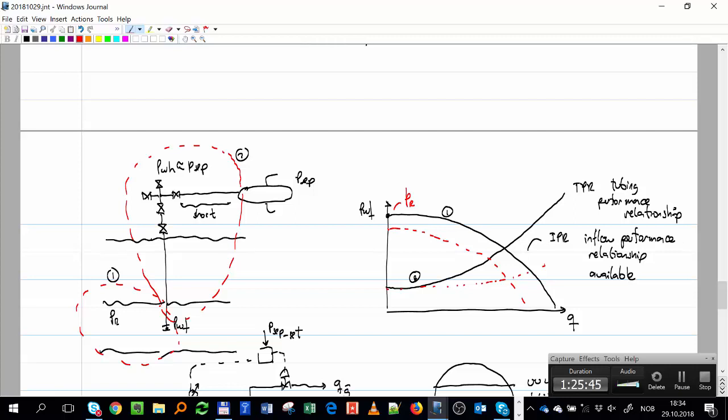So we take a break. Just one simple question. The same graph we put here, and for the second graph, what is that pressure? That will be separator pressure plus the hydrostatic column, either oil or gas, whatever I have, between the separator and the bottom.